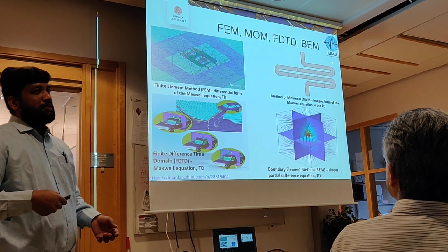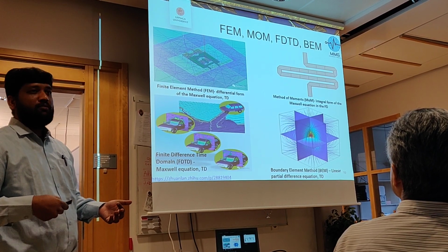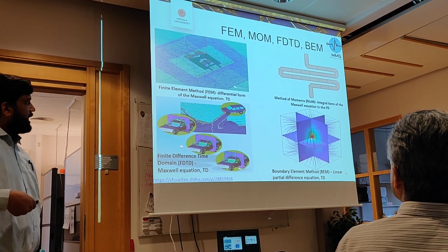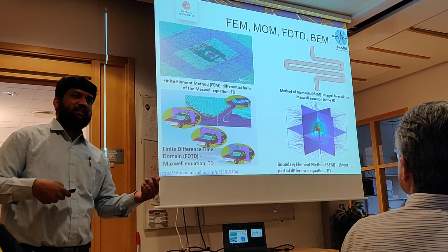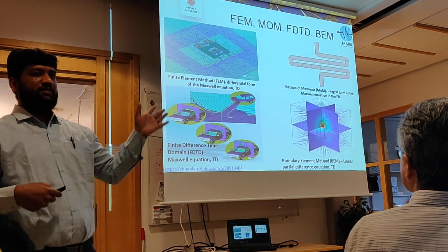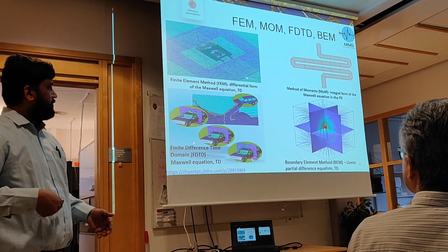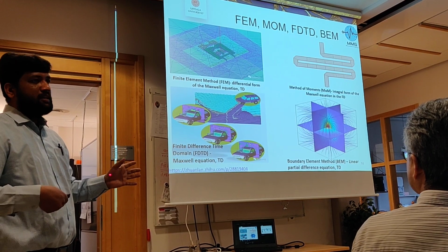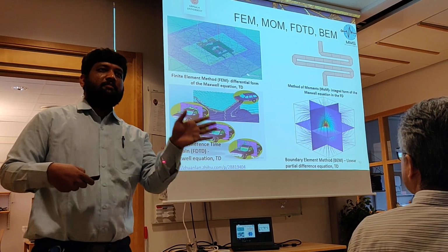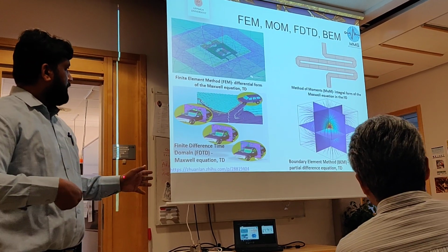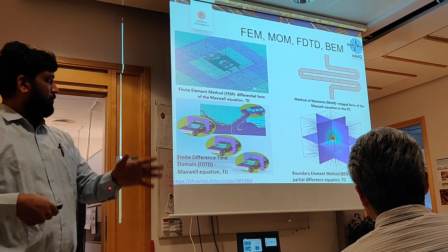This is basically for when you are dealing with a lot of complex active circuits, and we can go for it. Whenever we have a structure where we are looking at the electrical characteristics of a car or aeroplane or any of the different geometries in the world, you can go with FDTD, the finite difference time domain method. This is a completely 3D evaluation. The structure is taken and the evaluation is done with finite difference time domain, and it will apply Maxwell's equations in the time domain.